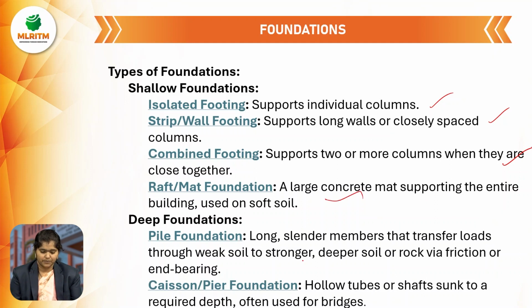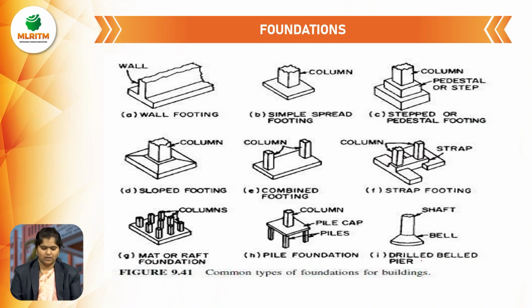Deep foundation, pile foundation, long slender members that transfer loads through weak soil to stronger, deeper soil or rock via friction and end bearing. Pier foundation, hollow tubes or shafts sunk to the required depth, often used for bridges.